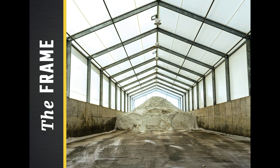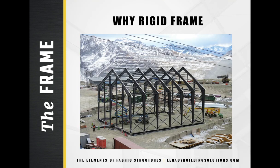The advantages of rigid frame construction include the ability to construct wide, clear span areas, engineering that complies with building codes, increased ability to withstand snow and seismic loads, increased ability to account for loads from cranes, conveyors, and other point loads, and cost-effective and energy-efficient construction. I'll turn it over to Dwayne Munt to talk about the frame. Thanks, Eric.